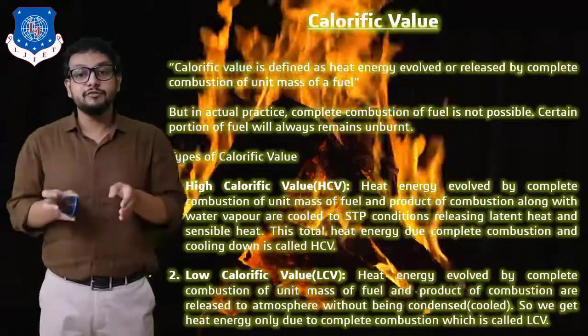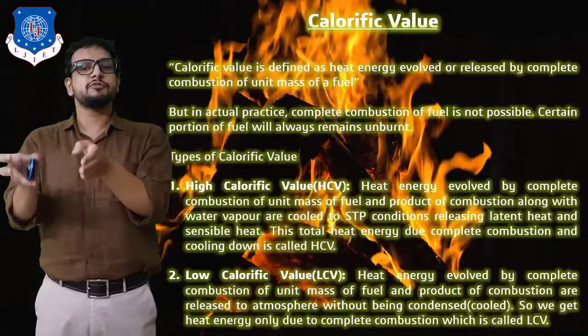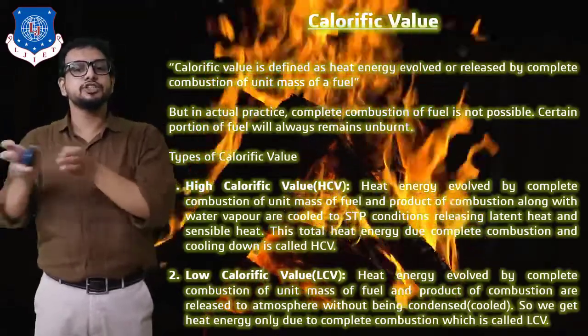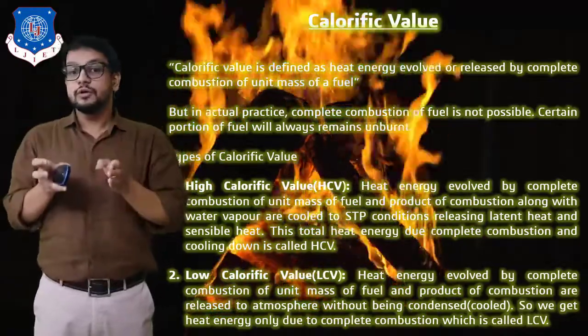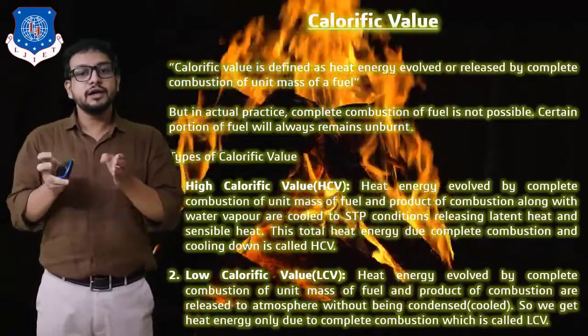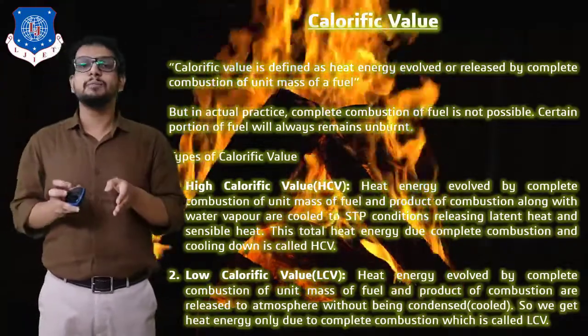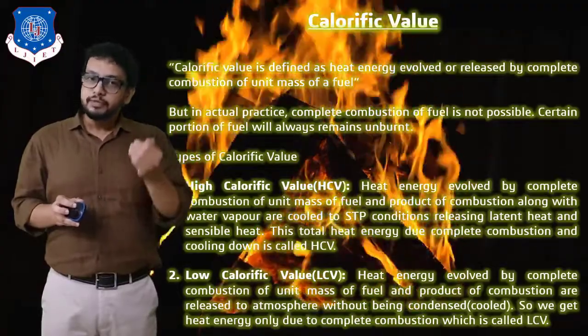As you can see, the definition: heat energy evolved by complete combustion of a unit mass of a fuel when the products of combustion are released to the surrounding atmosphere without condensing the water vapor. So we get heat energy only due to complete combustion of the fuel. That is called low calorific value.